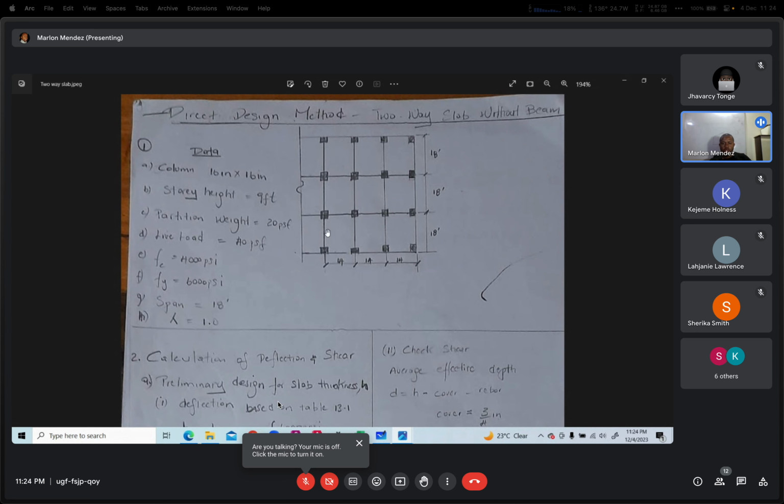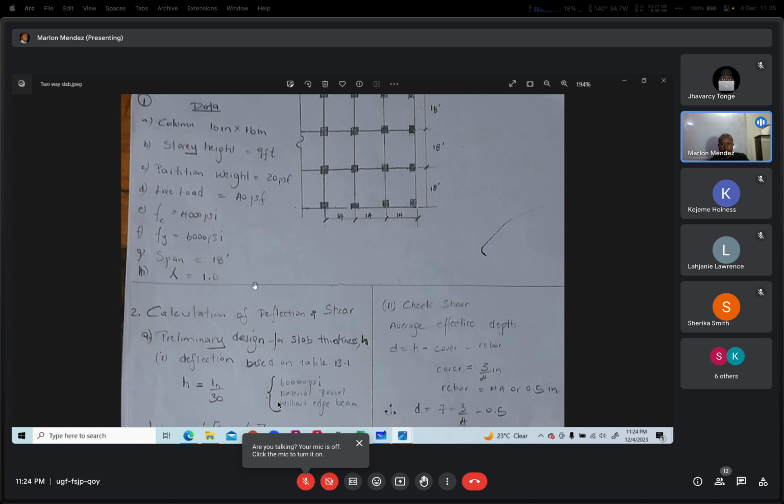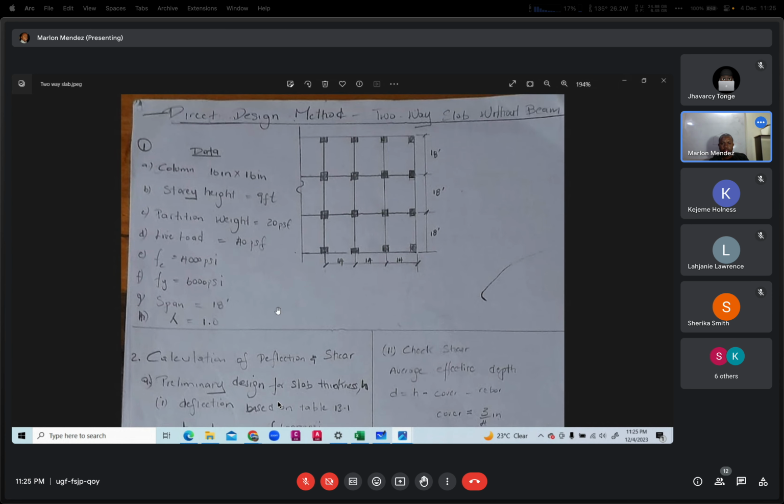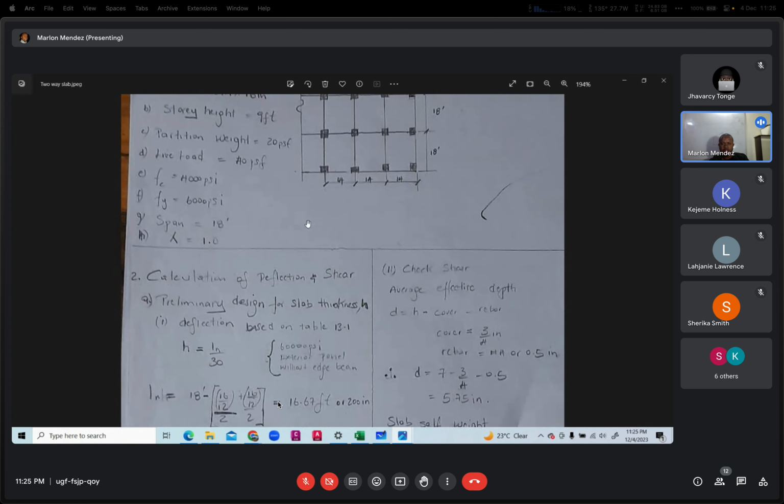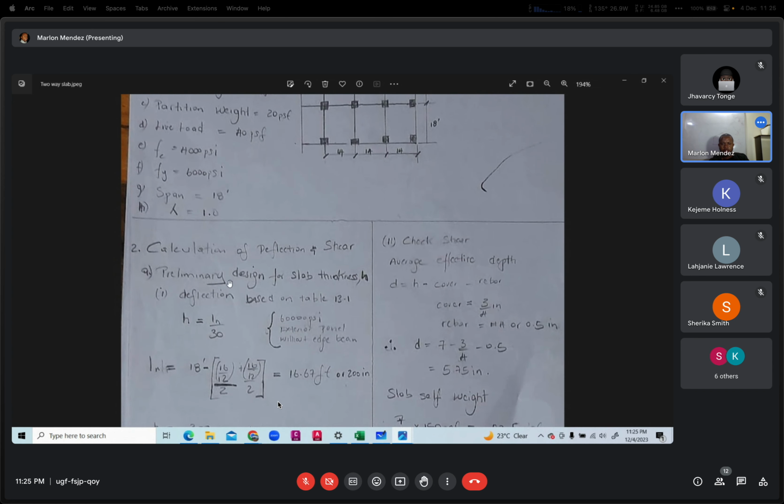You want to calculate deflection and shear force. I'm going to rule out shear force and look at calculating the moment on a one-direction slab, whether at the end or the column. In this calculation that I've uploaded, I think it only calculated the end, but in fact you also need to calculate the middle in terms of applying the formula.